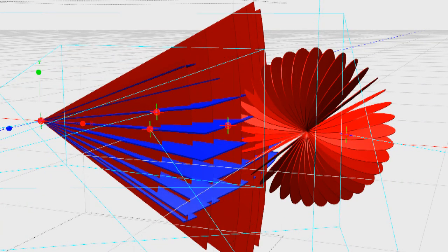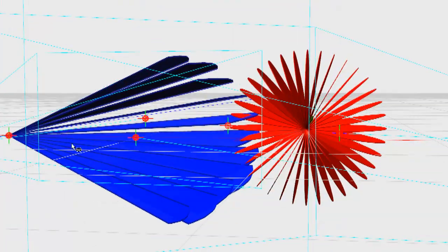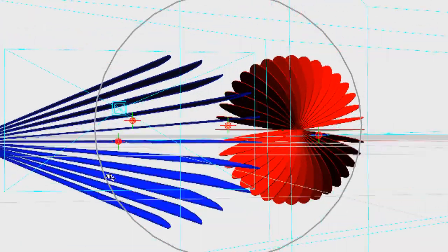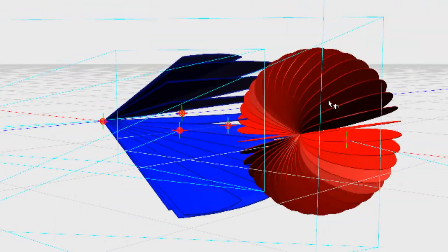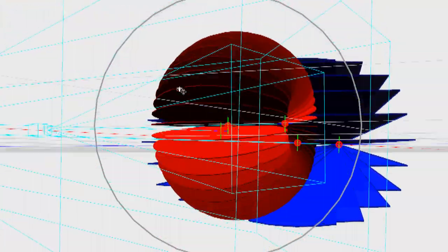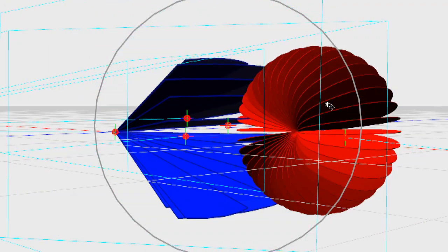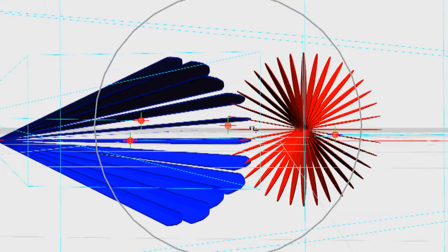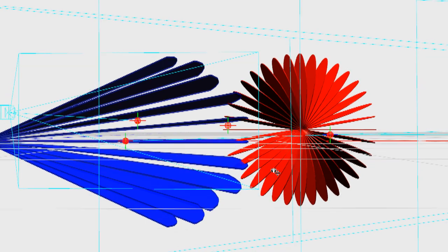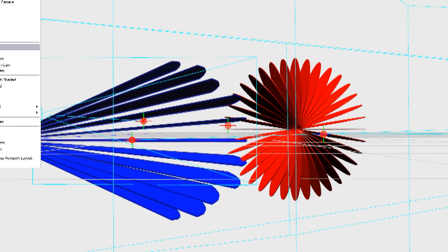So we can turn off the vertical one, and so this is how it looks for that. Again, it's about a 50 degree field of view, but the antenna is mounted internally at 90 degrees, giving you horizontal polarization. So this is linear diversity. There's a diversity between the polarizations essentially.